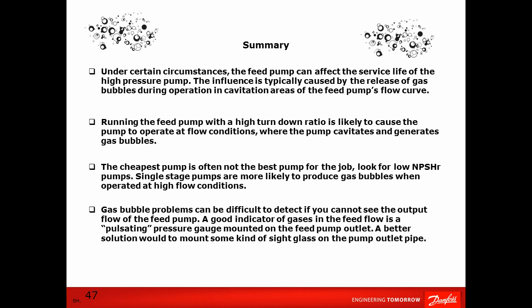If you mount a sight glass in the feed water inlet of the high-pressure pump skids, you can easily detect gas bubbles. We recommend that you install the sight glass in a bypass loop to keep the cost low and allow easy replacement without system downtime.